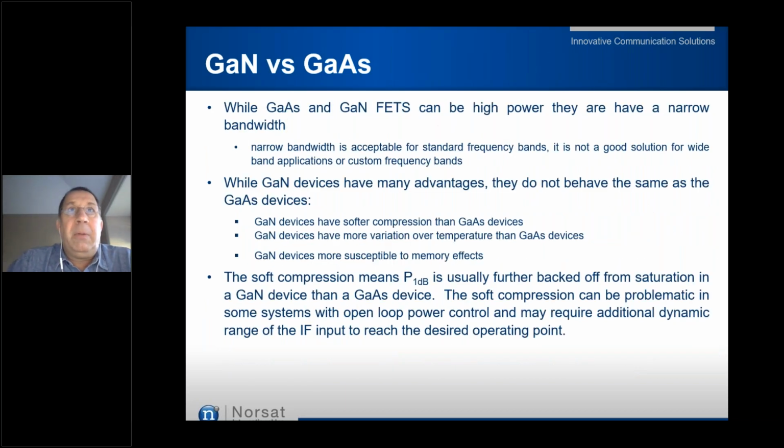The other thing with FETs is that they are high power, but they are a little bit narrower in bandwidth. They're designed that way. They're designed matched to a specific frequency band, which is perfectly good for standard frequency bands. They work well, but it's not a good solution for wideband applications or for custom frequency bands. So for bands outside of the standard bands, there are fewer FETs available.